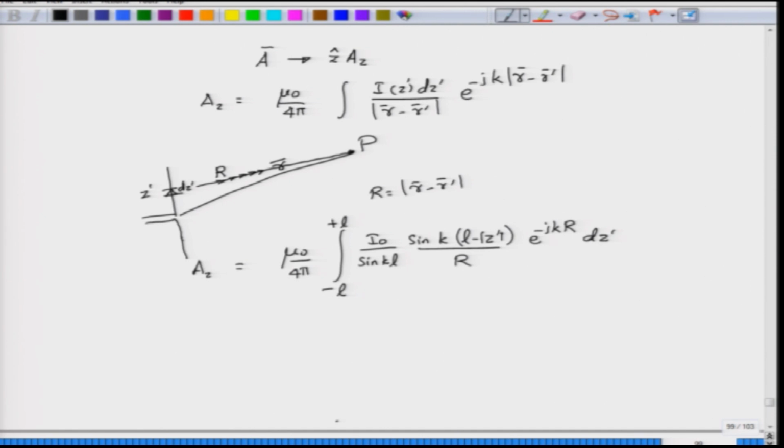So, we will have to make a couple of approximations, something that you may have seen earlier in the dipole scenario, but it is worthwhile to make that approximation. I am considering a particular point with a width of dz prime at a height of z prime, and then I am also going to consider a similar point at a distance of minus z prime from the origin, with a patch length of dz prime itself, and now I am looking at the observation point P here.